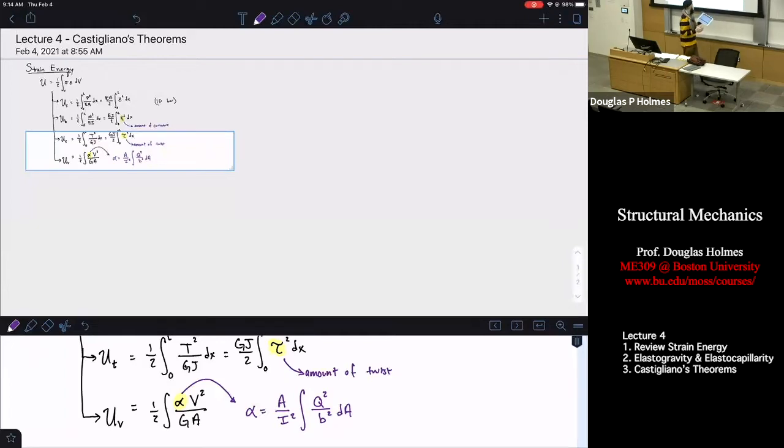We could work on figuring out how to calculate these things. I don't think it's particularly important. If you run a beam analysis in COMSOL, it's going to spit out half of these things for you just by drawing the thing in CAD anyway. But let me tell you what it is, just so you know what you're actually using here. Q is your first moment of area.